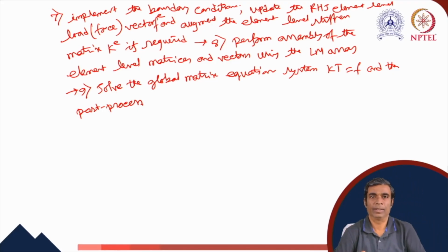So in a nutshell, this flow chart shows the FEM steps starting from the strong form. Here, the main difference from the variational methods is that we create finite elements and then we implement the variational methods per finite element such that at the junction of finite elements, when we have common nodes, the primary variable such as temperature, velocity, pressure, etc., must be continuous or have the same value so that we have a piecewise continuous distribution of the degree of freedom.